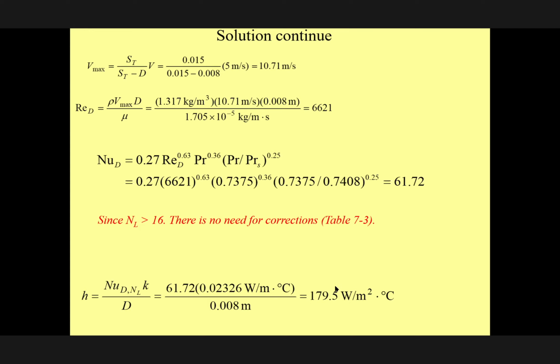Now we can go back. We know the h, we know the temperature difference, and we know the number of the tubes. We can calculate the energy exchange. Any question?